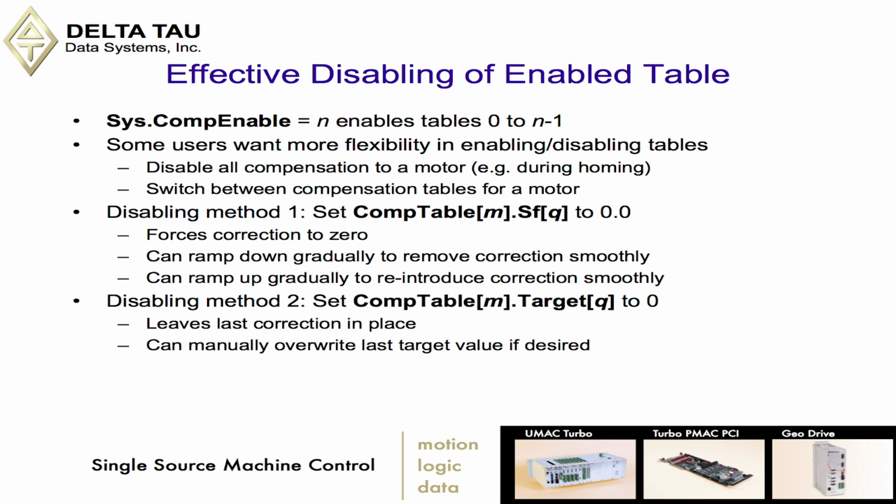The other thing you could do is set the target register address to 0, which effectively tells Power PMAC to disable that table, because now there is no target address. In most address structures in Power PMAC, if you set them to 0, the firmware almost always takes that to mean that you're disabling that addressable feature in Power PMAC.